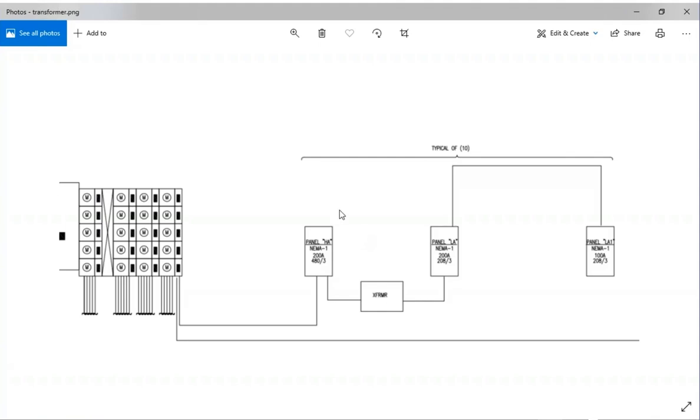That way you can get the load on panel HA. Then create a recurring panel template and have the loads on that, using fixed loads, match what your calculated value was for that typical. So you'll have to transfer the loads over manually. That's a manual step, unfortunately. And then you can insert that recurring panel as instances in various spots in the project. So you're not inserting all 4 of them, you're inserting just the first panel in the group with the corresponding loads, and then you have that called out somewhere else.